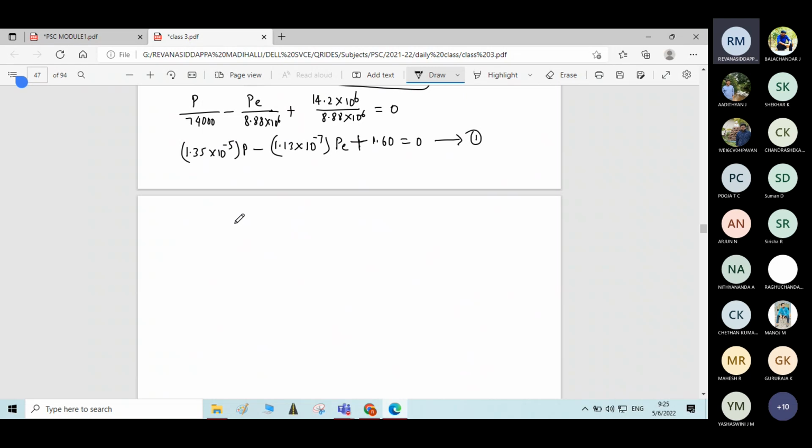Okay, during the service condition, what happens? There will be live load acting on the beam during service condition. Due to this live load, the bending pattern of the beam is vice versa, like this. Therefore tension occurs at the bottom fiber during service condition. Okay, when the live load is applied on the beam, this is the bending pattern. So tension occurs at the bottom fiber.